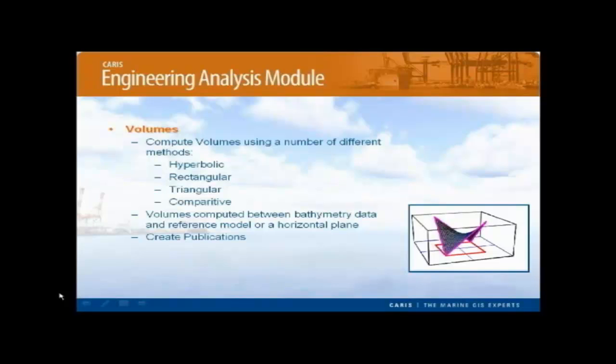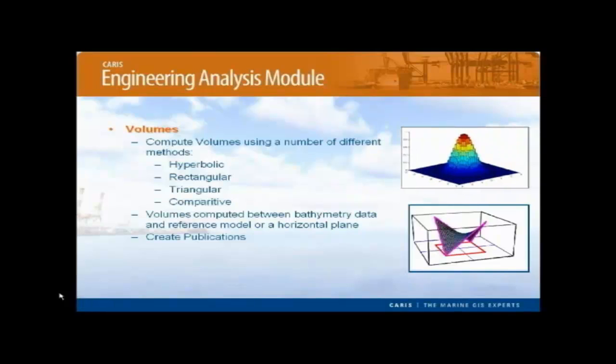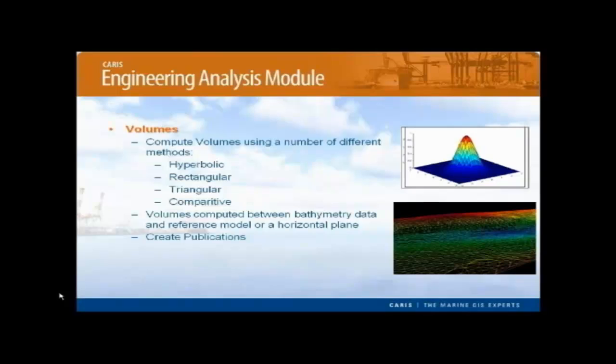Now we can compute volumes within Bathy DataBASE. A number of different methods for creating volumes are available depending on the user's requirement. First, we have the rectangle volumes to provide a simple, quick calculation. For a more robust calculation, the hyperbolic method can be used.